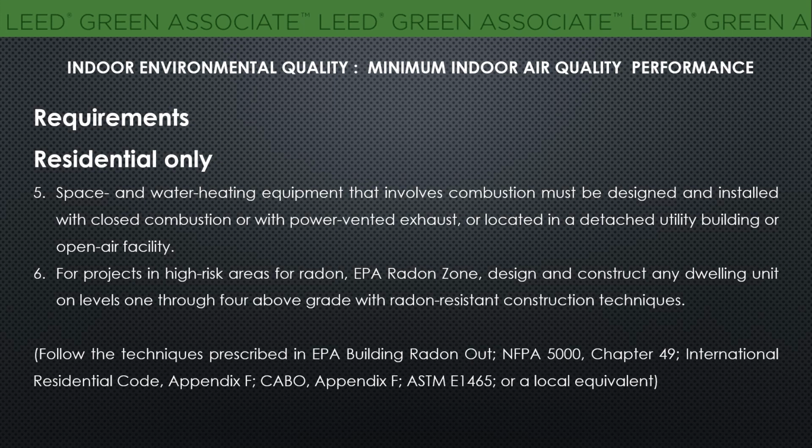So for projects in high risk areas of radon, EPA radon zones, design and construct any dwelling unit on levels 1 through 4 above grade with radon resistant construction techniques. LEED suggests following the techniques prescribed in EPA Building Radon Out, or a local equivalent.